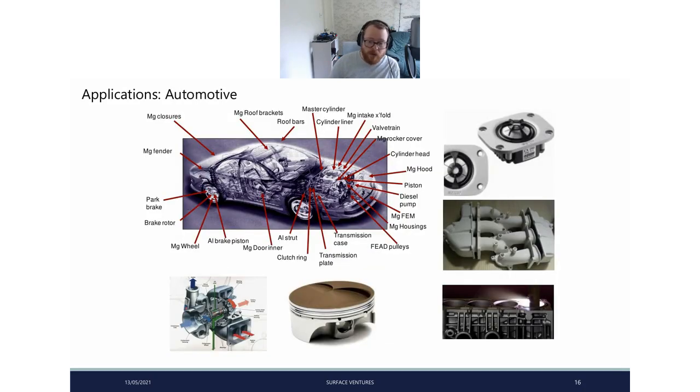Automotive, so quite a few things here. So surface hardening, so sections for pistons. You could have different coatings there, things like diamond-like carbon for wear resistance, low friction, coatings for bearings as well throughout the automotive structure. Paints as well, so protective paints is another big thing.